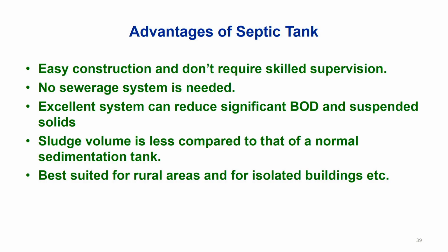So what are the advantages of a septic tank? First, it is easy to construct and doesn't require skilled supervision. No sewerage system, no network of pipes is required for this, and it can reduce significant BOD and suspended solids if maintained properly. The sludge volume which has to be dealt with is much less compared to a normal sedimentation tank, because anaerobic treatment is also happening, so some sludge is digested also, and it is best suited for rural areas and for isolated buildings.